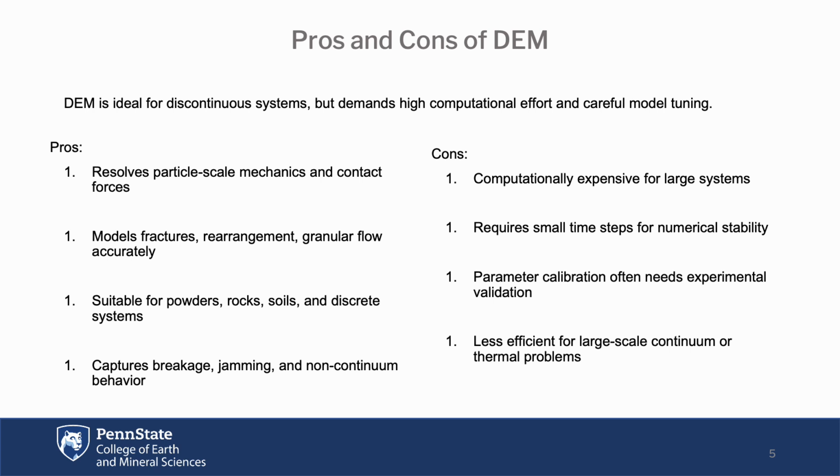Another challenge is calibration. While the force models in DEM are physics-based, their parameters like stiffness, damping, and friction must often be tuned or measured experimentally. This makes modeling difficult without experimental validation or sensitivity analysis.